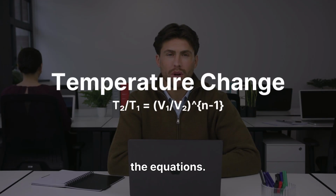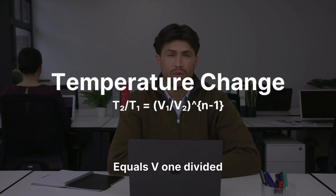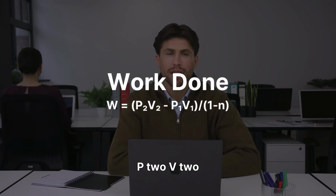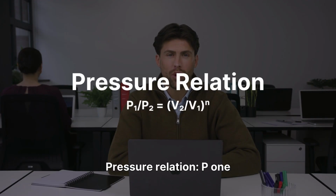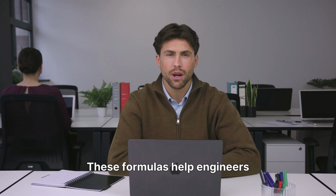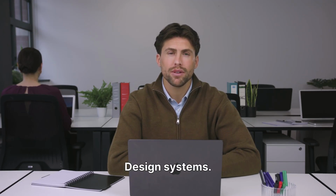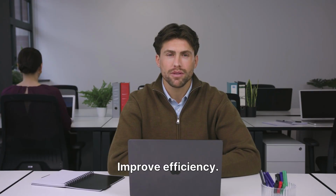Now let us see the equations. Temperature change: T2 divided by T1 equals V1 divided by V2 raised to power N-1. Work done: work equals P2V2 minus P1V1 divided by 1 minus N. Pressure relation: P1 divided by P2 equals V2 divided by V1 raised to power N. These formulas help engineers to calculate power, predict temperature, design systems, improve efficiency.